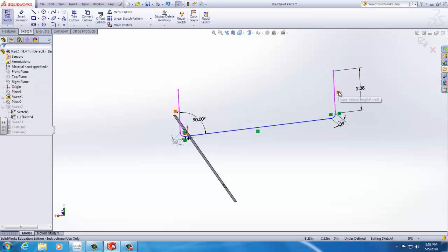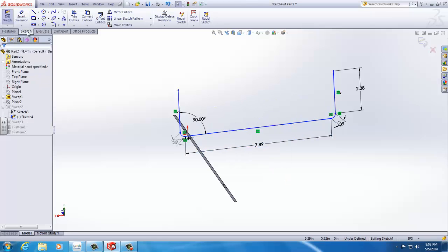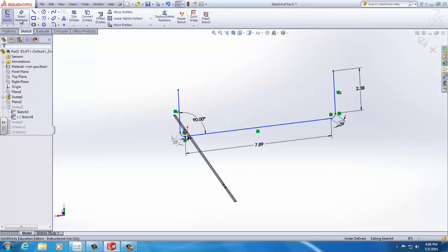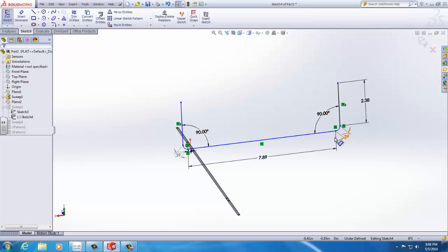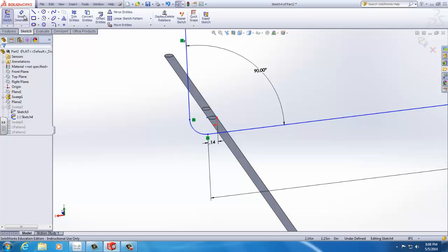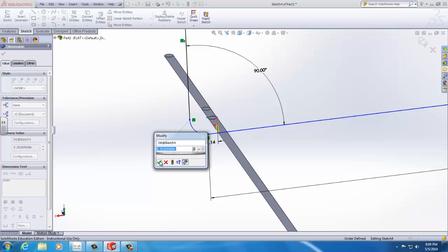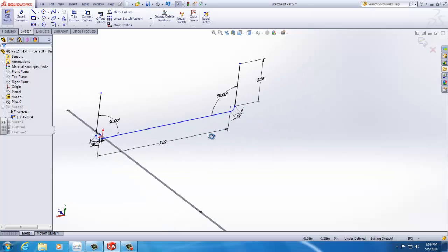Anyways, we're going to mirror it. We're going to use the front view for our mirror. Select the object or bodies. Usually bodies. If the face features don't work, use the bodies. Now I have to figure out why it's not working. Okay, so what I was supposed to do is not thicken it first, I'm supposed to mirror it first, then thicken it. I made that mistake.